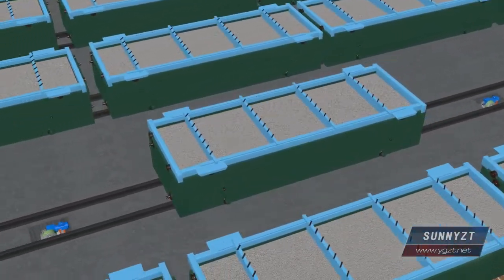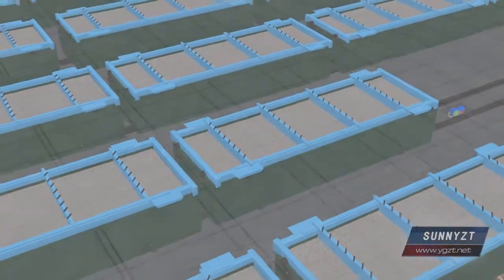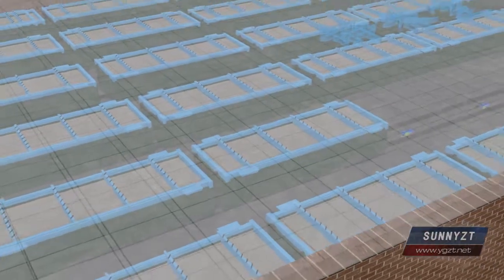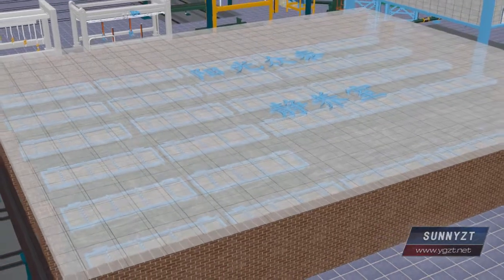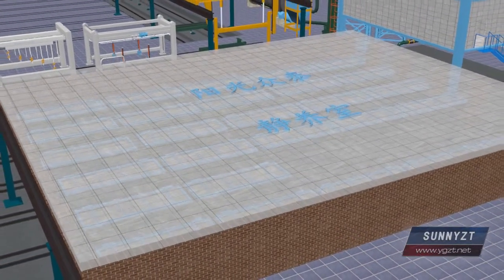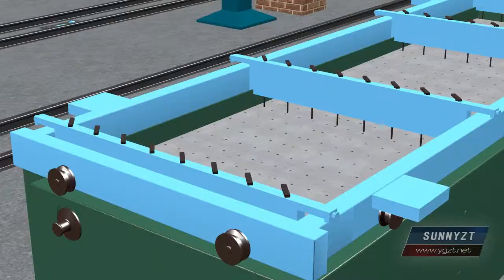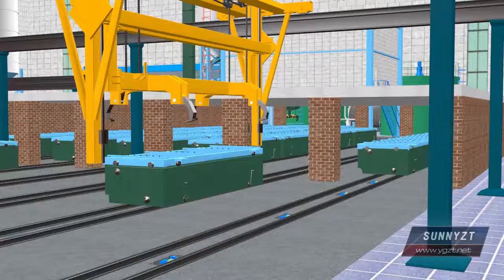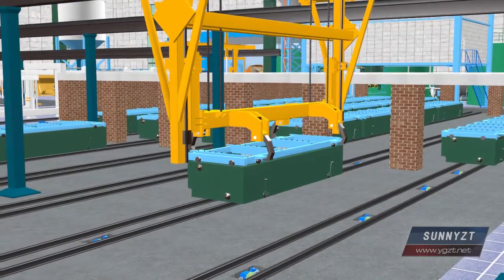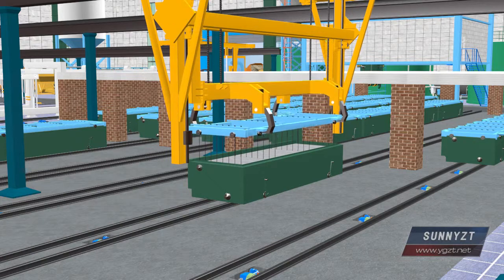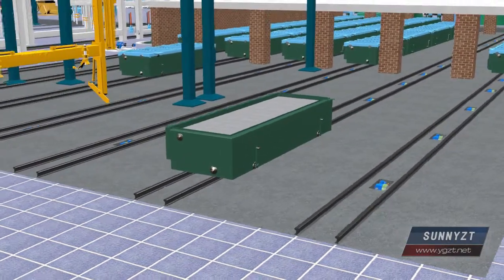After completion of pouring, enter the stage of gas developing and static hardening, after a series of physical and chemical changes, including gas development, densification, and initial setting. After that, use the friction wheel to convey the hardening molding box to the position for pulling the drill rod. Pull out the whole drill rod clamp with a pulling crane. Take it to the flipping crane with the friction wheel.